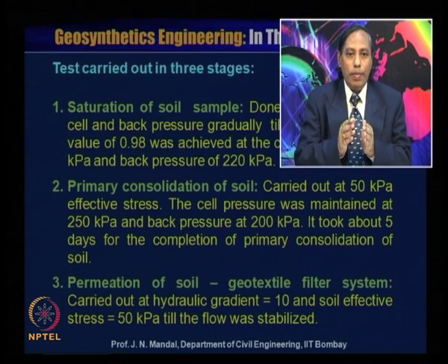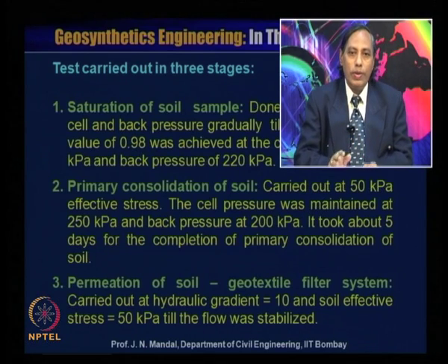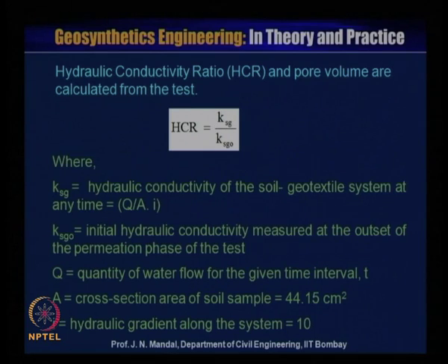And thirdly, permeation of the soil geotextile filter system was carried out at a hydraulic gradient equal to 10 and soil effective stress equal to 50 kilopascal till the flow was stabilized. So then hydraulic conductivity ratio and pore volume flow are calculated from the test.